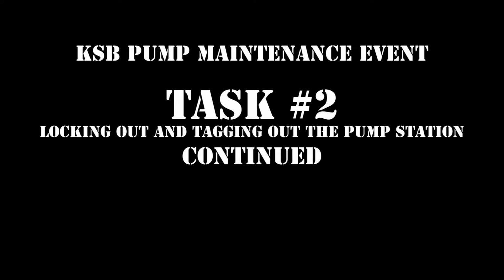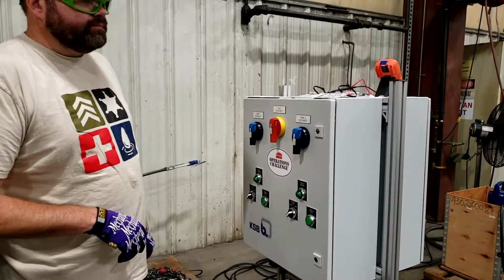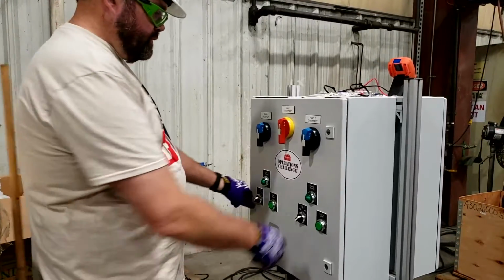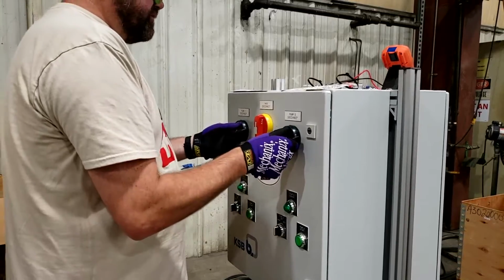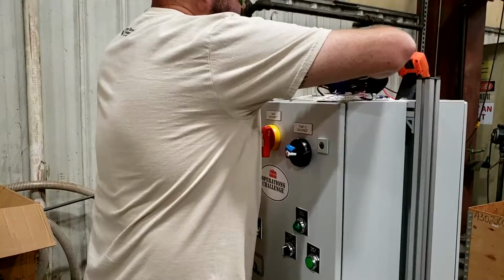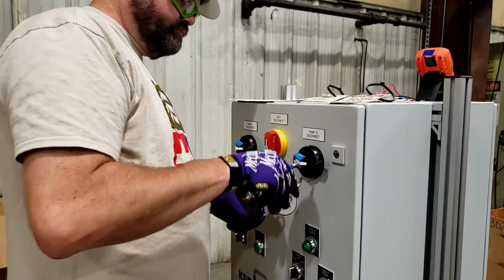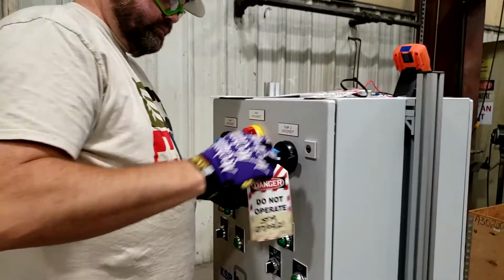We are now continuing Task 2. Lock out and tag out the pump station. On the lift station control panel, turn pump 1 and pump 2, the hand-off auto or HOA switches, to the off position. Put the pump 1 and pump 2 disconnects in the off position. The safety supervisor must install a gang hasp, lock, and tag on both pump 1 and pump 2 disconnect switches.